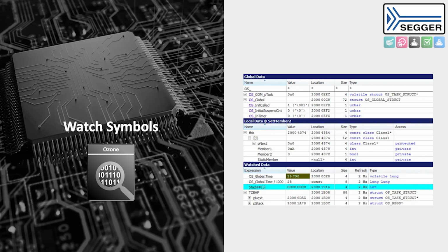Standard operation in a debugger, of course, is inspecting symbol values while the target is halted, and this is available with all three access methods and usually done using the program buffer, as it is implemented most of the time and it has core view into memory. But most debuggers also offer watching symbols and periodically updating them while the target is running.